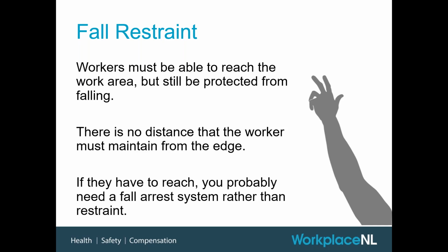I do want to highlight that there's no specific distance in our legislation that says this is restraint, this is arrest. But the general rule is, if you have the potential to go beyond the edge or opening, then you need arrest. I always like to think of whether or not the worker is going to have to reach to get to whatever it is they're working on. And if they really have to overextend in the restraint system to try to do their work, then you may be in a situation where you really need fall arrest instead of restraint.